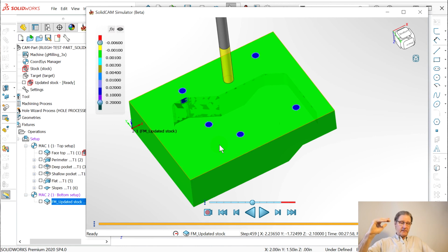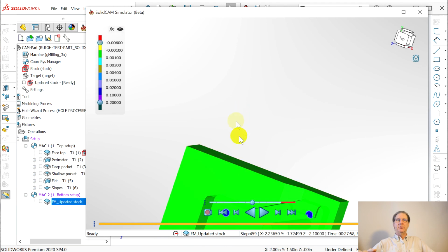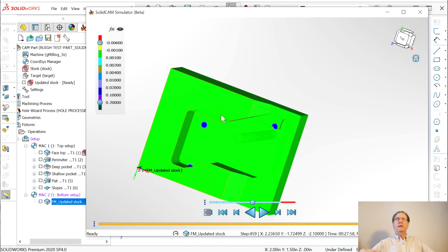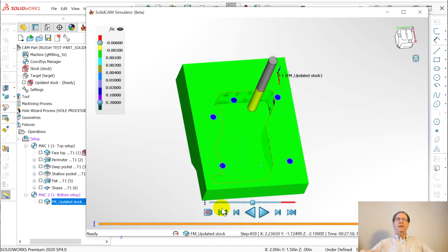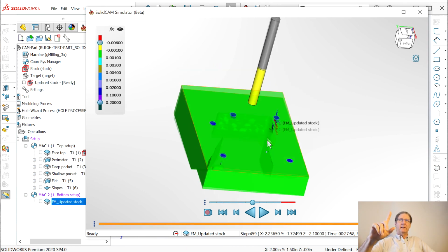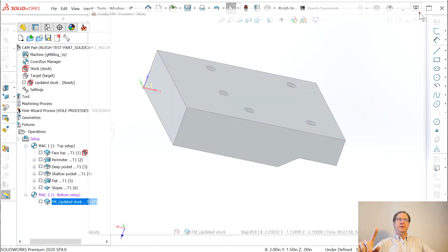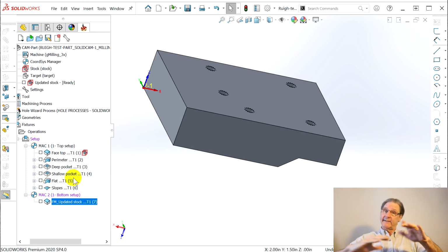And like always, like SolidWorks CAM by CAMWorks, the automatic feature recognition wants to do 2 from the top. It wants to do these 2 on the top, and then do these 3 on the bottom. And I think it splits those up, whether they're blind or not, and you get all these toolpaths and all these tool changes. So I think I tried automatic. I'll practice for you folks so you don't have to watch me stumble around. But like usually, it's easier just to do them individually. And then we can use that save as a copy if we want to save the 5 hole locations, right? But that's so easy.